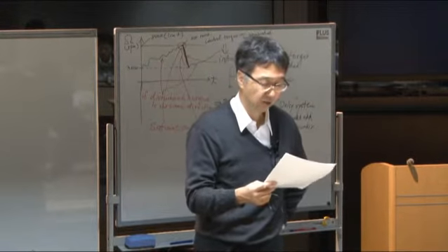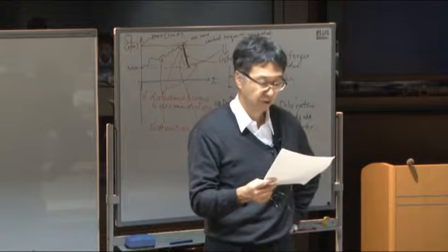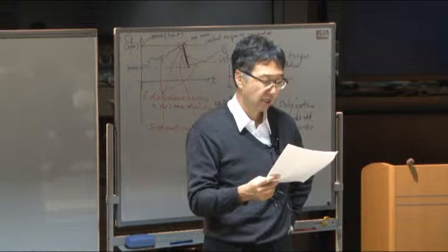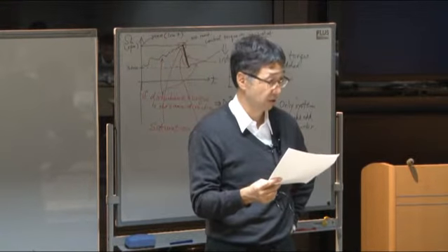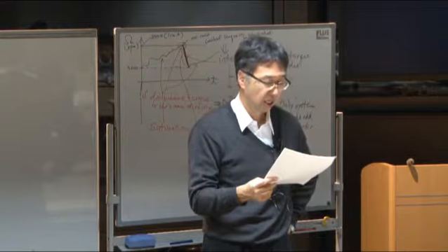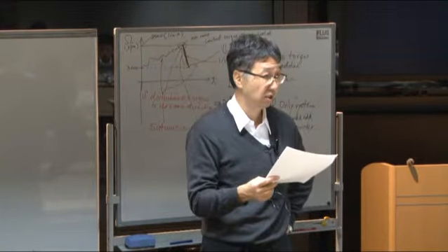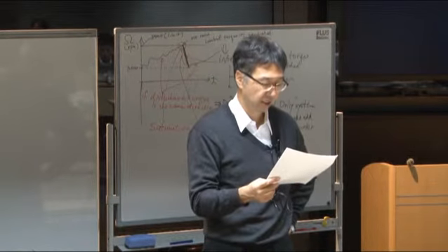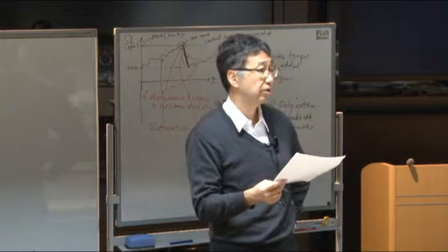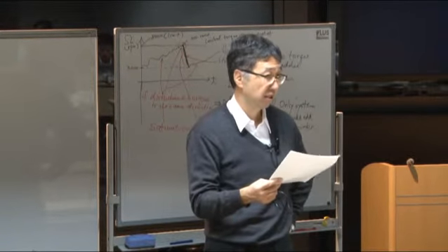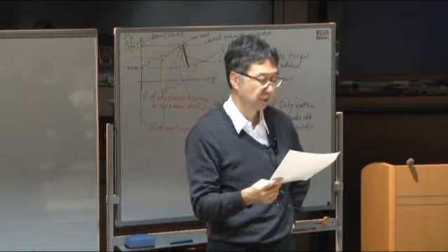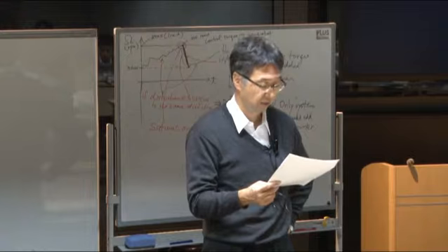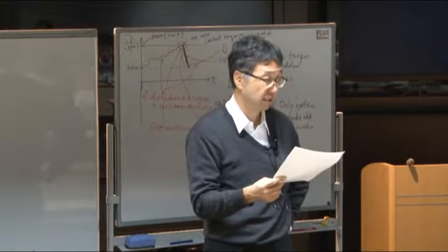But if the eccentricity gets larger, 0.05, 0.1, 0.2, 0.3, then the angular velocity should be changed periodically, depending on the position on the ellipse. Okay, maybe you see it very easily. So that's why we want a circular orbit. It's very easy. Once you get a rotational speed of the satellite, that speed should be kept constant. Then we can obtain the Earth-oriented attitude of the satellite.